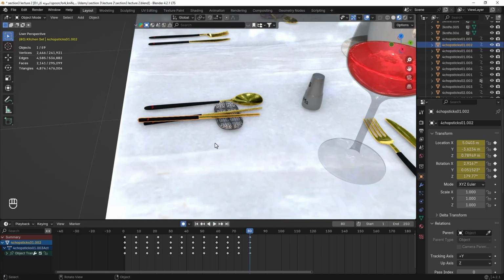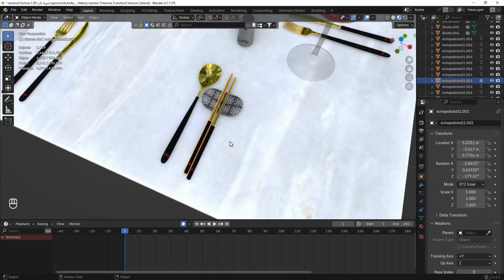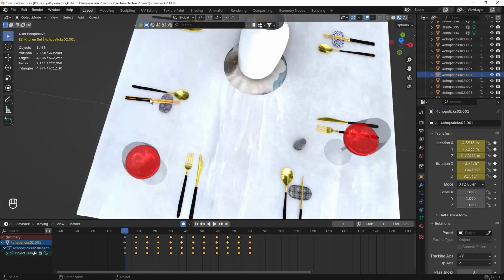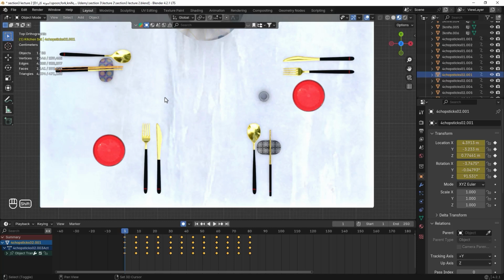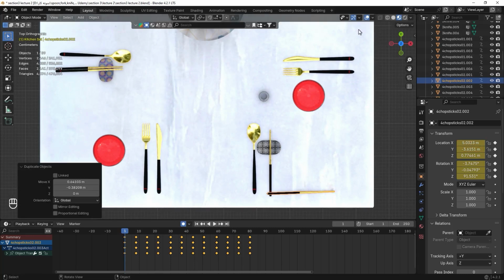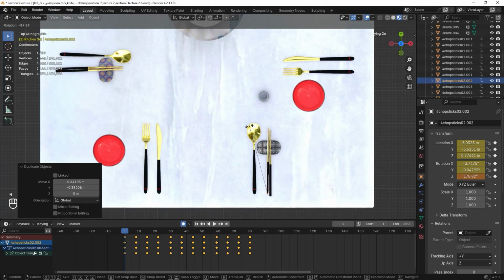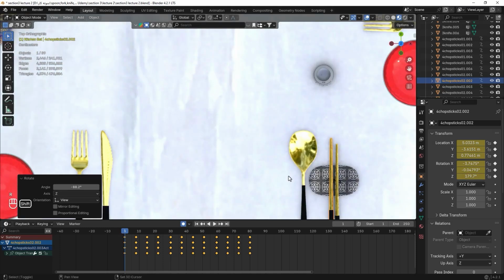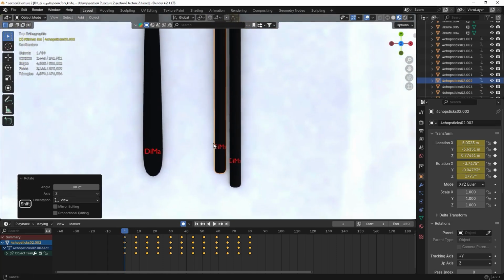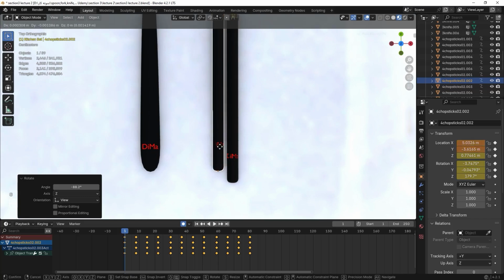it. So then we remove the left chopstick and then get a duplicate of the one on the left from the previously animated chopstick, and move it to the gray and white holder, and then with pressing the R key we rotate it almost 180 degrees, and we set and fix it on the holder in the right place.